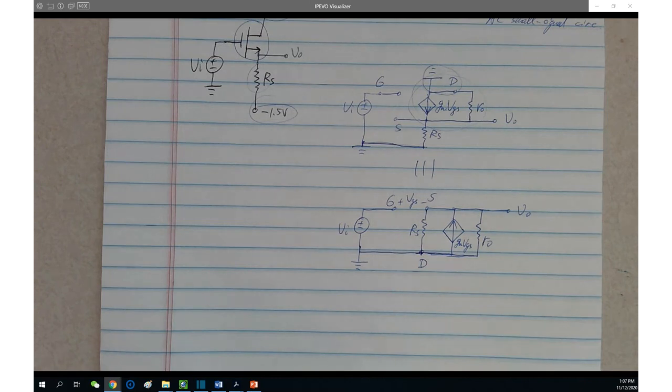Yes, in finding the Thevenin equivalent circuit you have to find its Thevenin equivalent resistance. However, that is not the equivalent resistance across any two ports. I suggest you differentiate these things. They're not exactly the same, though very close.